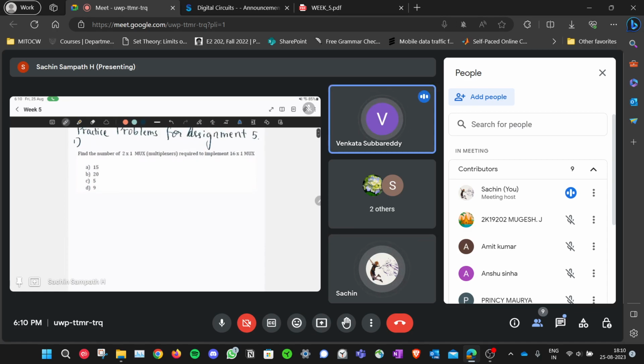See, this adder was also built with AND gates and NOR gates. Only these things, right? So you write down the truth table and use a K map and minimize it, and whatever you get, you make a circuit that can add three numbers or four numbers. You can do it.